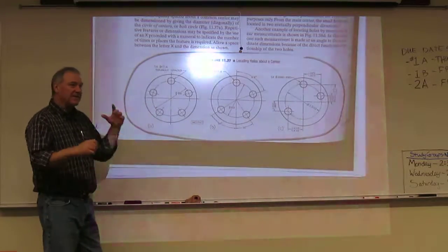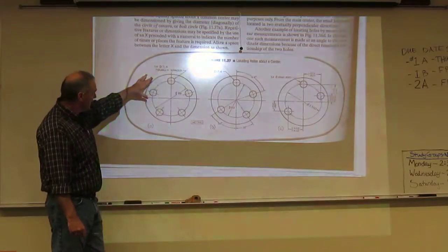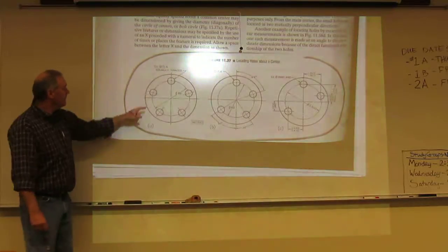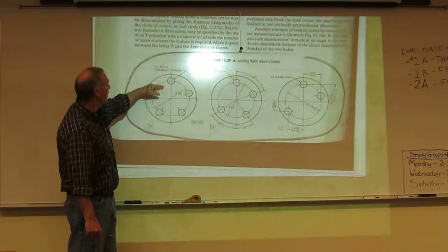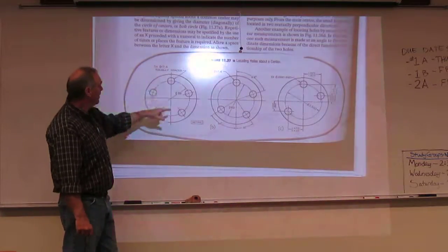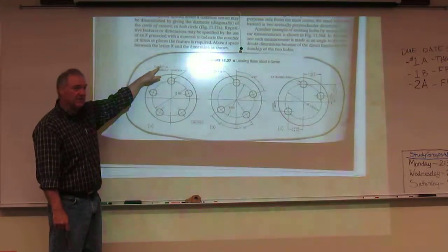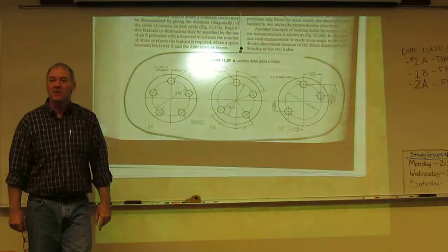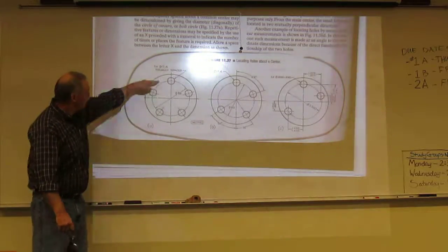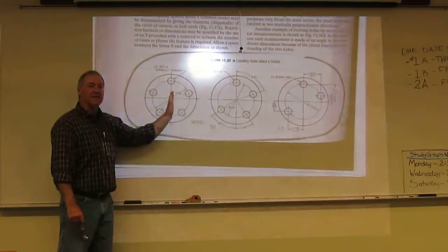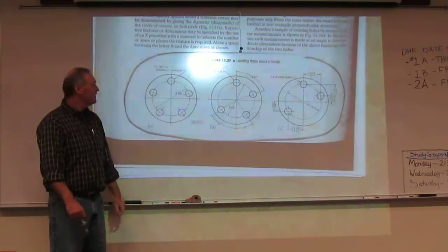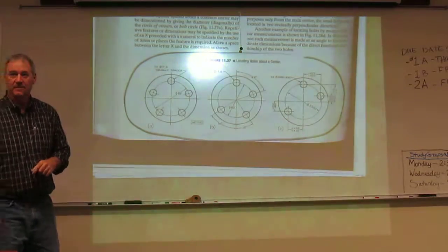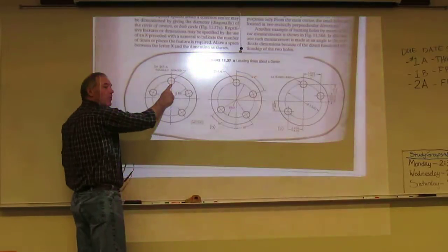So this is where these can just save you a lot of work. Now when we're looking at this one, there's 5 of them on here. They're equally spaced. So they've gone and used the multiplier, 5 by 17.4, and then they put equally spaced. Now notice where they've attached the size dimension to. They've attached it to this one. They did that because it's going to locate in your X and Y direction. This center line locates from the center out. So in essence, with some center lines here, we've taken all the locationing out of these holes. They put it on this one because it's on a quadrant location.